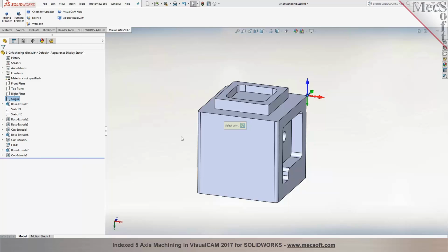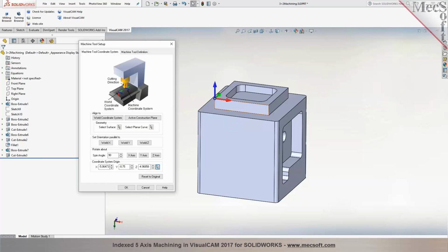If you want to move the origin to a different spot, you can hover the mouse and cursor pick, and you can specify it, you can pick a point. So this will change the XYZ0 origin. So again, rather than moving the part to XYZ0 in your CAD, that you typically are familiar with doing in Rhino or in the standalone product, in this particular setup, you just pick where the origin needs to be. So you establish that. Let me ask you a question.